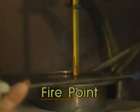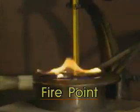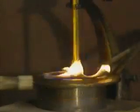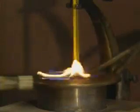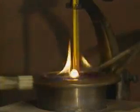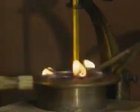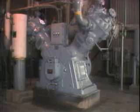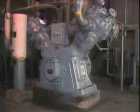The fire point is the lowest temperature at which the lubricant will burn steadily when it's exposed to a source of ignition. This occurs because enough vapor is created to cause continuous burning. If either the flash point or the fire point is exceeded, a fire hazard exists. Resistance to oxidation is another significant property of lubricants. It refers to a lubricant's resistance to reacting chemically with oxygen when exposed to heat and air.